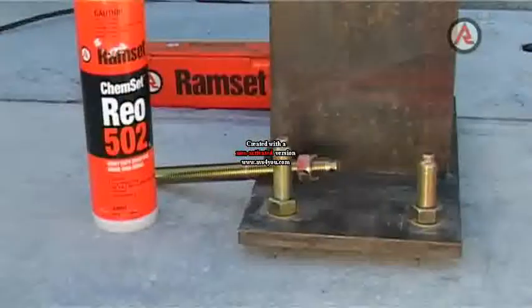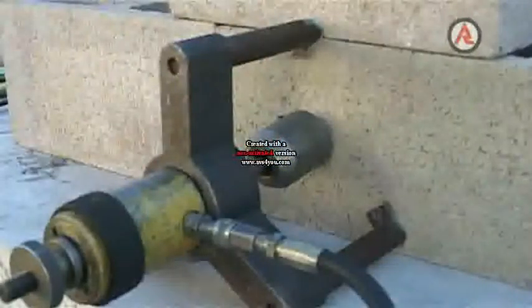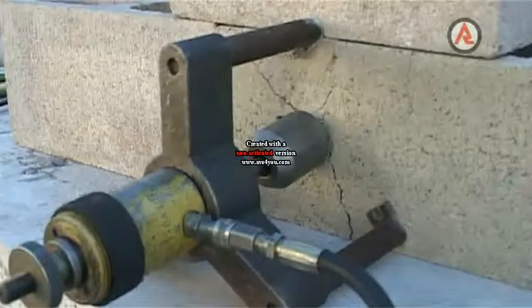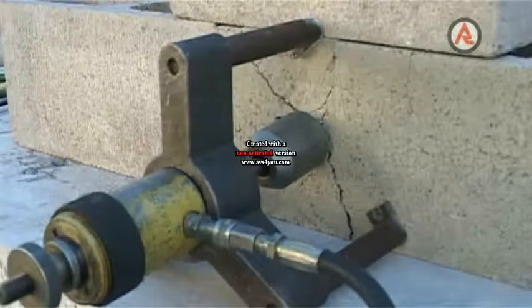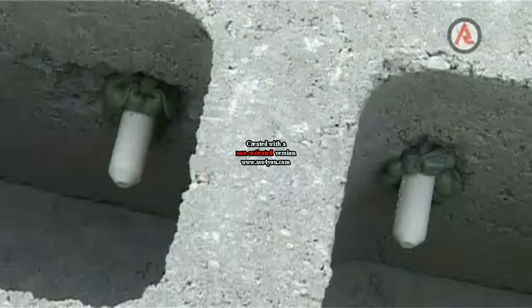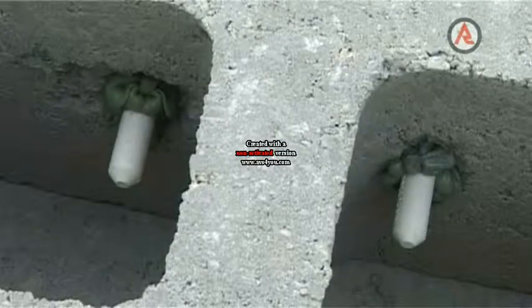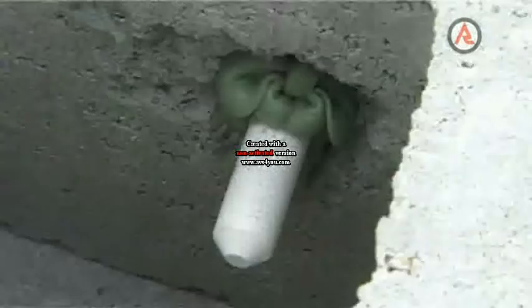the surrounding material. In hollow masonry materials, the tensile load capacity is dependent on the shear load capability of the thin section of brick or block. The objective in hollow materials is to spread the load over as great an area as possible to increase the load potential of the fastening.